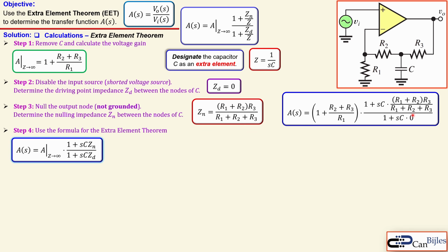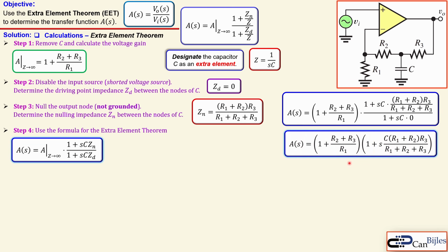So we will actually have here 0 plus 1, which is effectively 1. So you divide this by 1. Effectively you get now this result. You see here also clearly that this is a time constant, which is now in this case first order, and this is actually a differentiator circuit. Now the zero frequency here, because there's no pole, the only zero frequency here is determined by 1 over this time constant. And that is also, of course, a minus sign because it is in the left half plane.